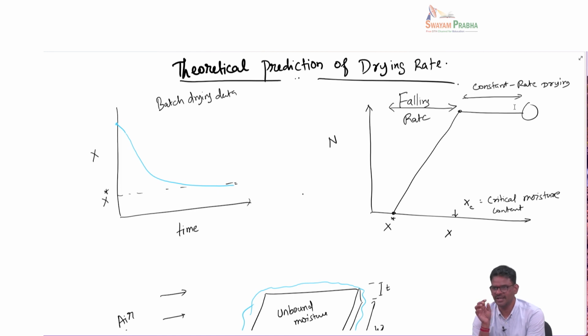I'm not saying equal. I'm saying something close by. So I'm not saying Tg and Ts should be close, because then I would basically have a very long drying period. What I'm saying is, even if Tg and Ts are quite different, the sensible heat required to heat the vapor from Ts to Tg is going to be comparably less compared to the latent heat required for evaporation. So the reason for that assumption is different from the other assumption.